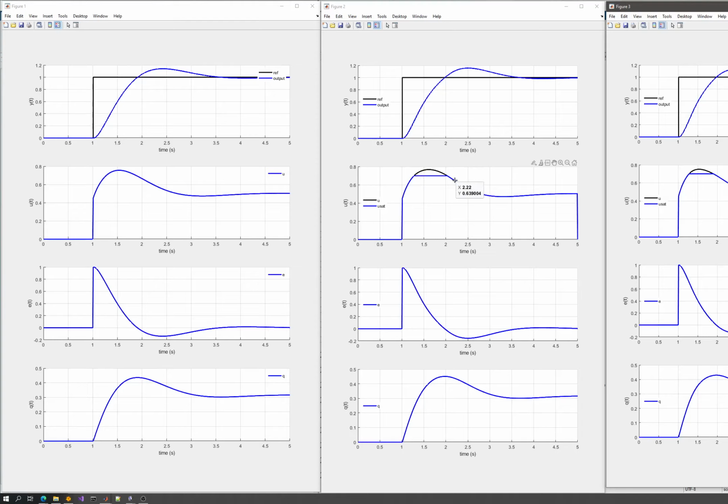and this is a more ideal control in terms of the saturation, because if you have a restriction, then you should choose your time specifications accordingly. If not, then this wind-up structure will be a bigger problem, and it will force you to a certain point. But know about this anti-windup structure, and a P-type controller during saturation and a PI controller during other situations is not a bad idea. So you might want to look for that.